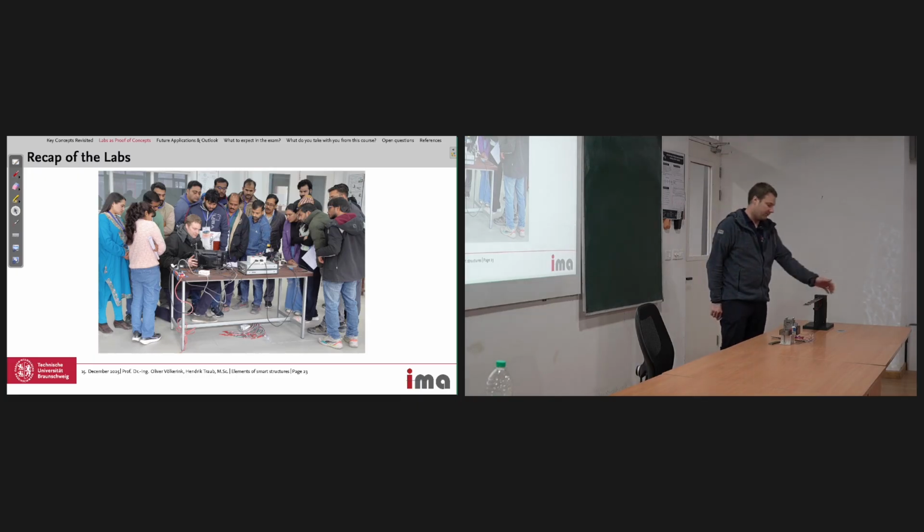And we first of all determined the eigenfrequencies, the first two eigenfrequencies of this beam. By the way, you can calculate them as well. But today we determined them experimentally. And we took the measurement of the displacement here and determined the frequencies. And after that, we tried to get the mode shapes by determining the displacement at several points along the length. Okay?